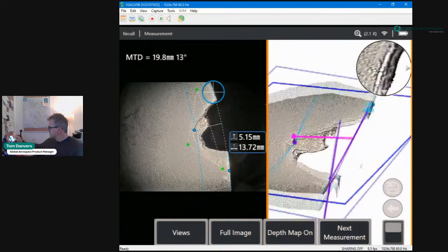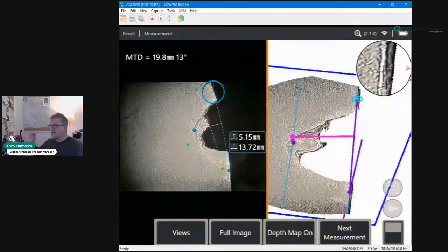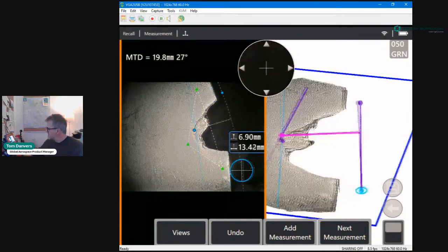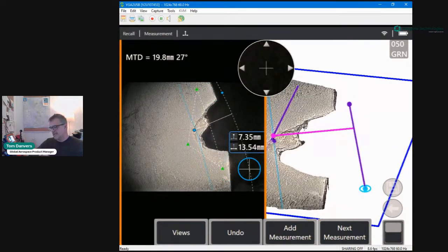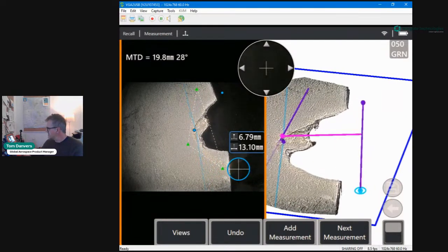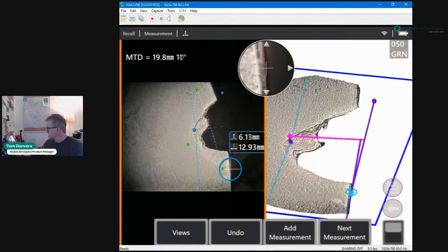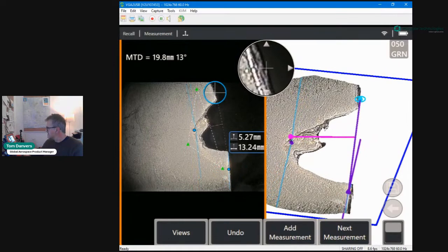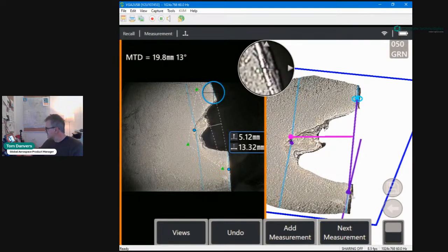So using a measurement plane is a fantastic way to make sure that you've got a really good, accurate measurement. And just to reiterate, if I move the cursors out into space, I'm still able to do that because I've now applied a measurement plane to this surface. So you've got to be careful, once you're working with a measurement that has a measurement plane on it, that your cursor positionings are appropriate.